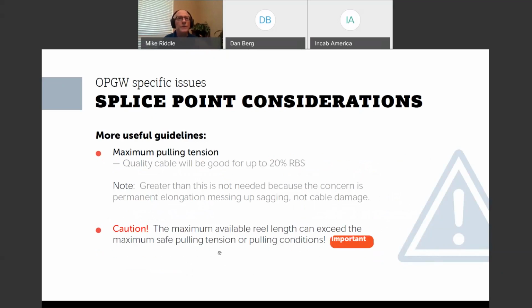That happened to a customer here in the United States. They bought 20,000 foot reels, and then the cable manufacturer told them pulling restrictions that basically limited them to something like, I don't know, 15,000 feet. And when challenged on it, the cable supplier said, well, you just asked if we could make it. You didn't ask what we could actually let you pull in. So you got to watch that.